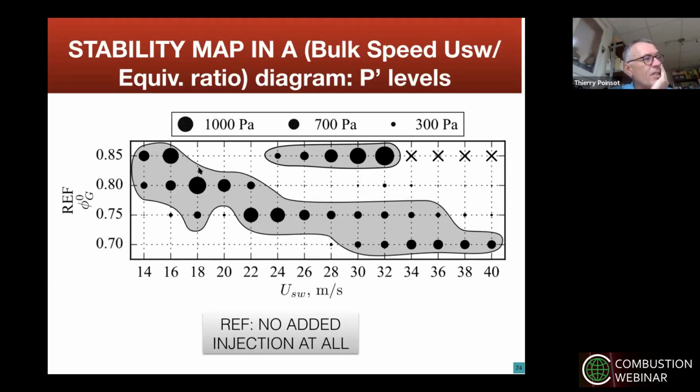And you see that this is a typical gas turbine plot. Means, yeah, there are cases where you cannot go. For example, these 4 points here, don't even go there because everything will explode. Here it will make a lot of noise. And these points here, where they look okay, you can operate things here. But you see that there are many places where you cannot go, especially if you want to go very lean here, or if you want to go to a very small power, this chamber will oscillate.